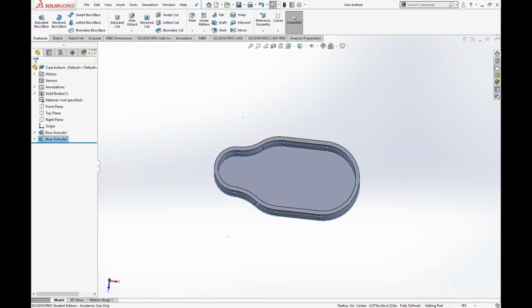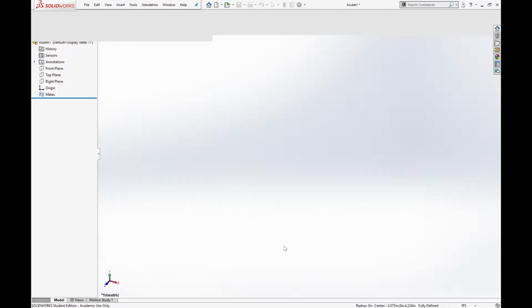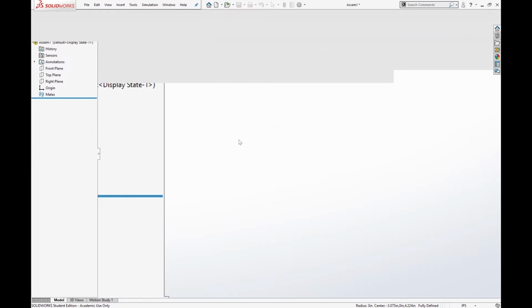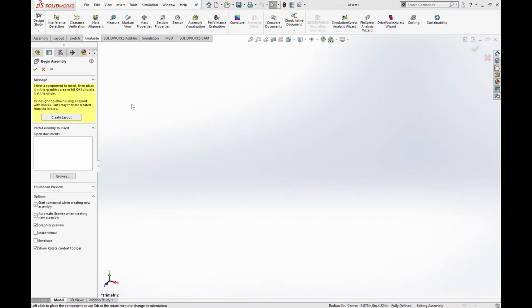So now that we have that saved, let's open up an assembly. So we're going to go File, Open. Oh, sorry. File, New. We're going to create an assembly. Alright, once we're in our assembly, we're going to bring in that case bottom. We're going to open.